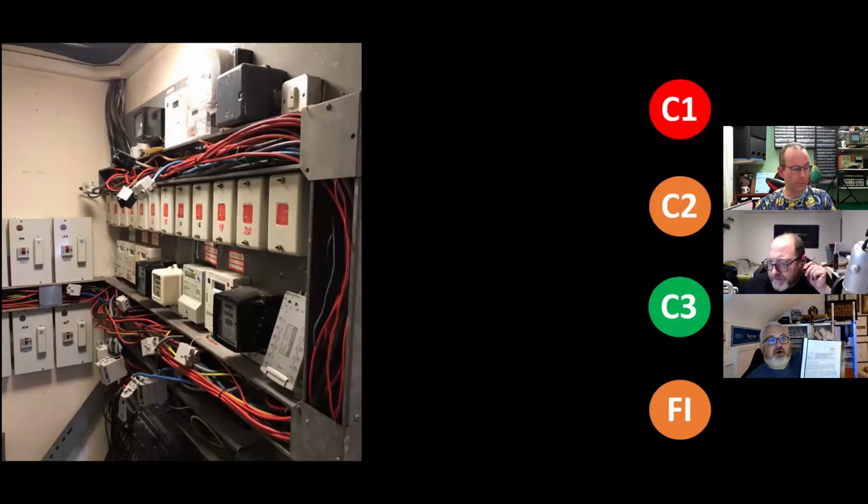So this is the Ofgem. Just to let everybody know, Ofgem regulate the DNOs, and on 13th of September 2013 they said there is a concern that by giving a fixed maximum earth electrode resistance value of 20 ohm, this is taken as the default value. The rise in potential is not calculated and proved to be safe.